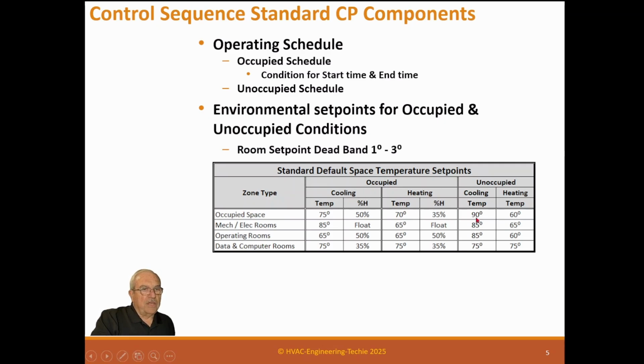And the calculation you have to do to prove what that is, is how much energy you use getting from the setback temperature to the setup temperature versus how much you save using that higher reset for the unoccupied period. And of course, you can reset it as high as long as the recovery period is not using more energy. The building is unique, so you have to calculate it for that building. But my gut feeling is 85 is a much safer bet than 90 degrees.